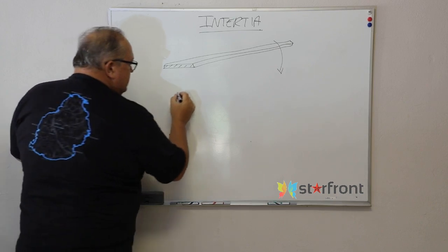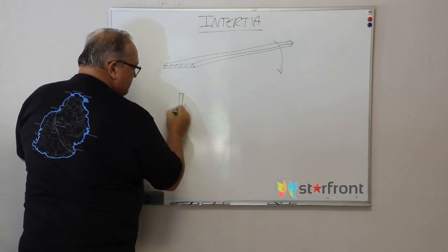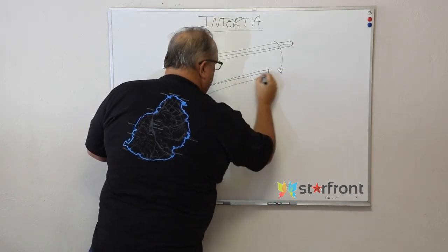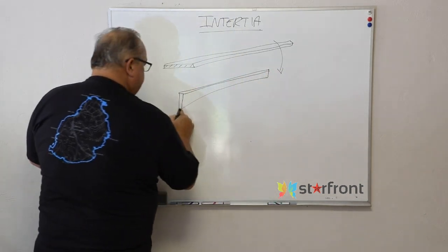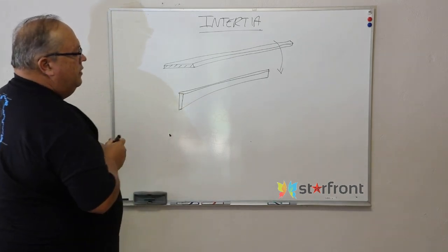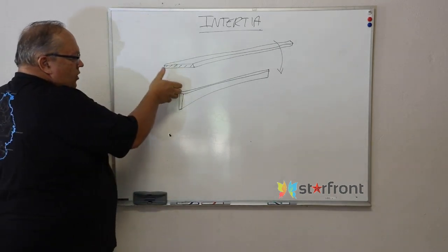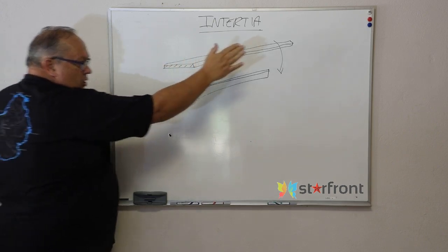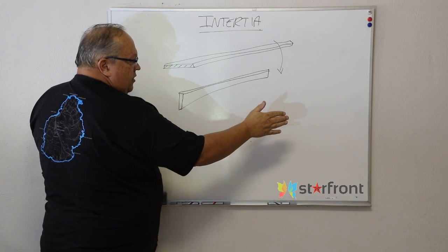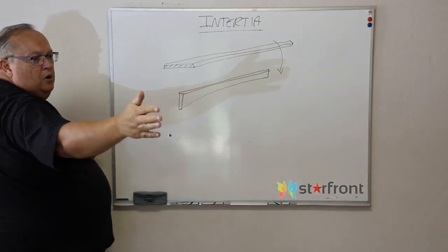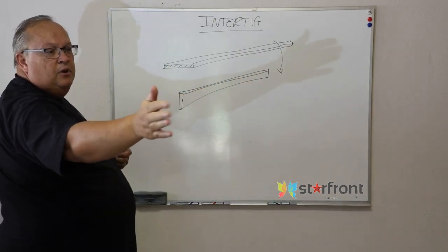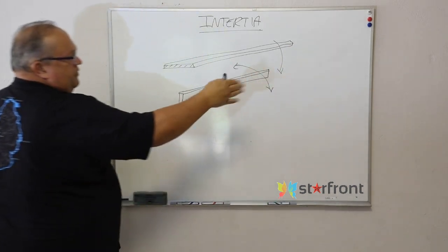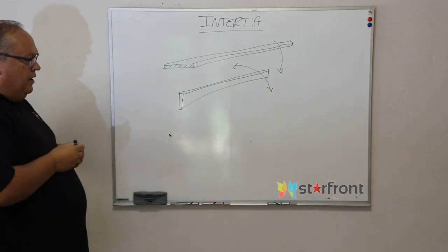But now I take that exact same aluminium profile, my piece of flat bar, and I hold it in this orientation. Not a very nice drawing. Okay, what happens now? If I hold that bar, just holding the end of it, alright, that bar will no longer sag at the end. But what will tend to happen is that bar will start becoming flexible in the horizontal direction. So it will start moving left and right as opposed to up and down.